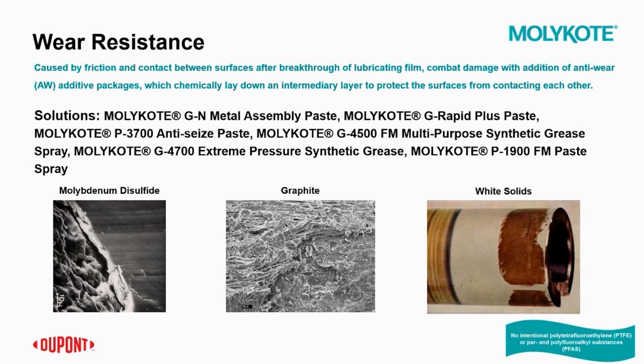Lastly, we could have white solids used as additives that also enhance wear resistance by offering a thicker lubricating film that could withstand much higher loads. So really, MOLYKOTE offers a host of products, as you can see from our solutions that are listed, that incorporate either some or all of these additives in order to increase wear resistance in a given application.